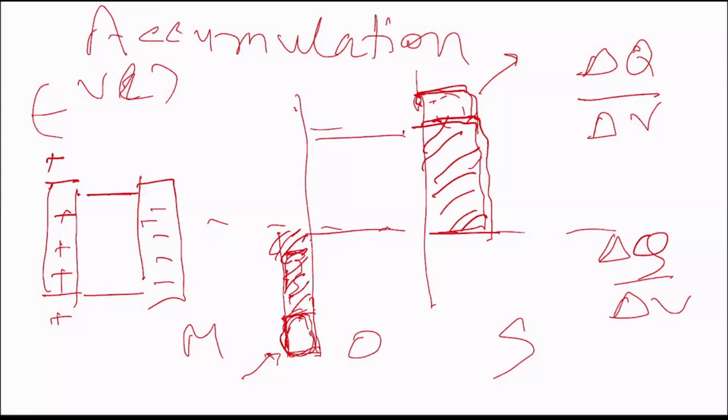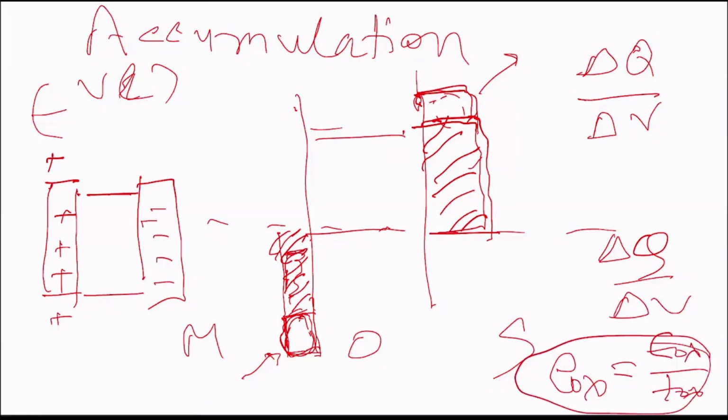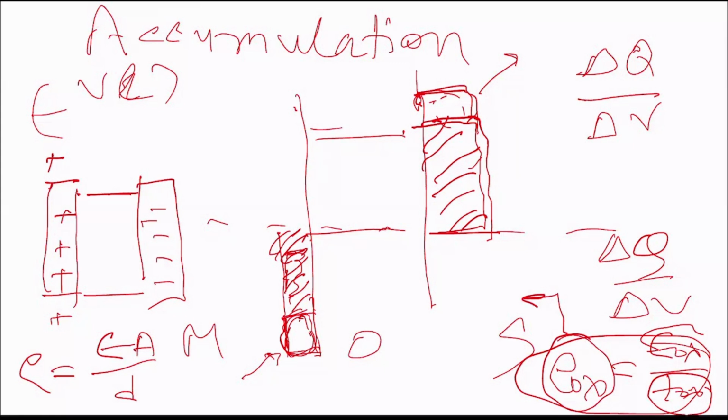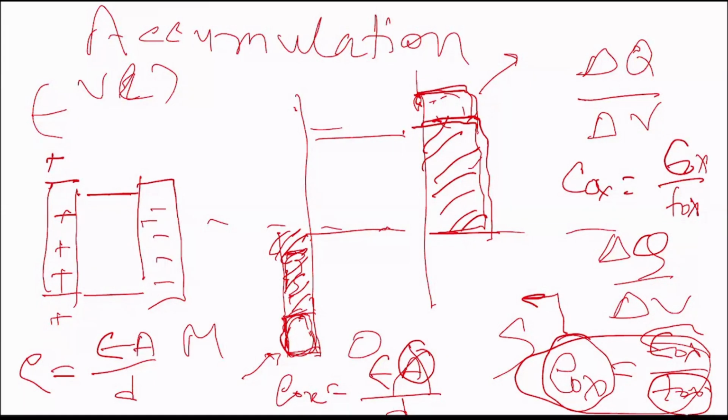And if you remember, the formula of oxide capacitance is, if you remember the capacitance of a parallel plate capacitor, which is basically epsilon A by D. But here, for C_ox, the capacitance in a MOSFET or this kind of transistor is described per unit area. So there is no A. You see, for a parallel plate we have epsilon A by D, but here there is no A. For oxide capacitance, we have epsilon_ox by t_ox.